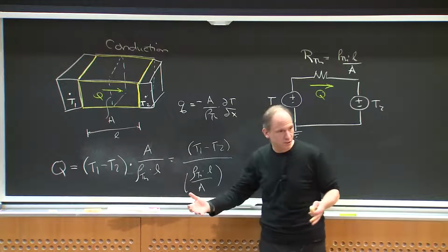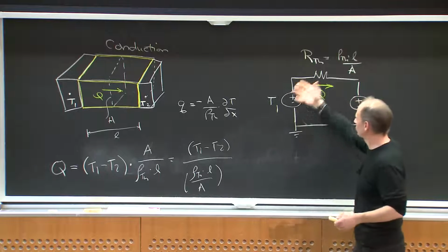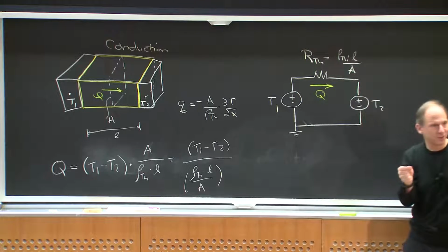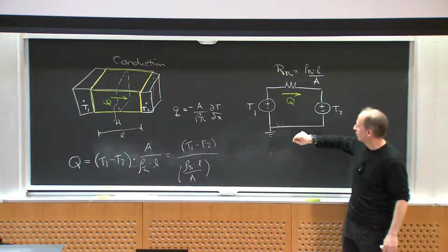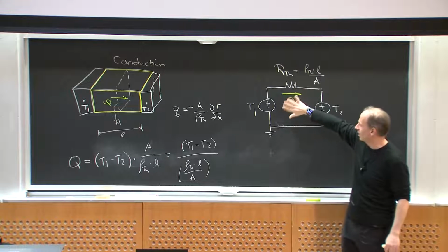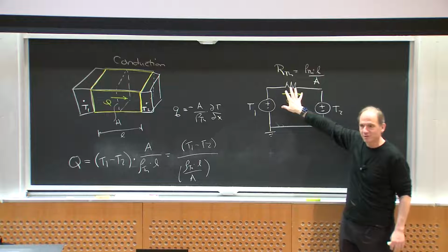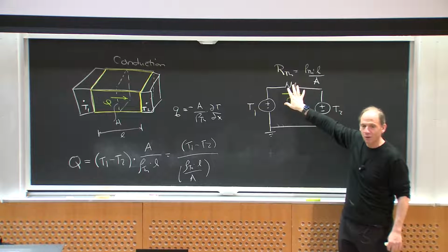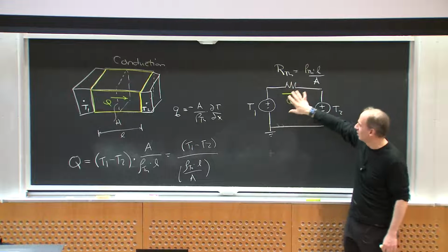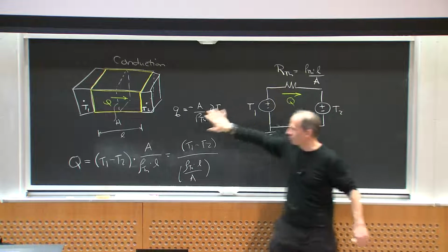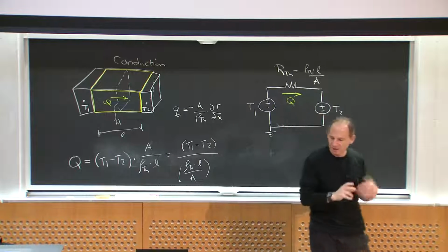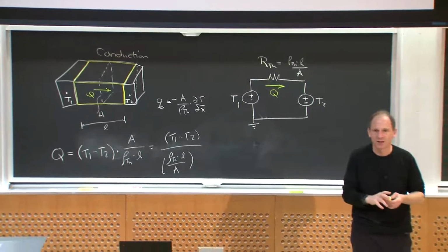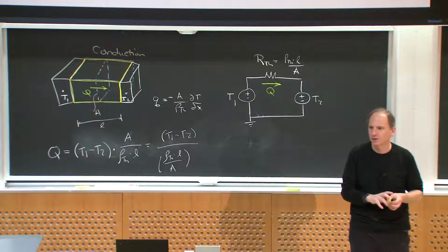The reason this works is sort of temperature is conserved going around any loop, right? If I measure temperature differences around a loop, I ought to get zero. And if I consider heat inputs and heat transfers, conservation of power is sort of the equivalent of KCL in this circuit model. So I'm showing you a simplified circuit model for a very particular kind of heat transfer, but you can use this model to represent heat transfers in a variety of conditions. Any questions about that?